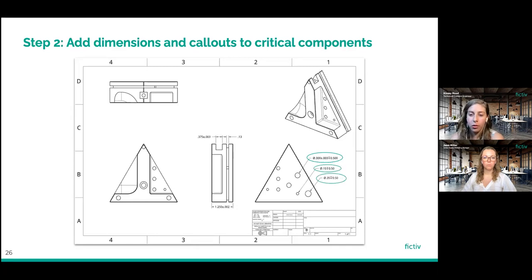Similarly, these two holes are not as precise. They also have a depth call out though, so more blind holes. Next, we are going to this hole with, again, no tolerances here. We do have a depth associated, and we also have the second line this time that's calling out a thread call out. So this hole is going to be tapped with a 1/4-20 UNC tap, and it's going to be tapped to a depth of 0.63.